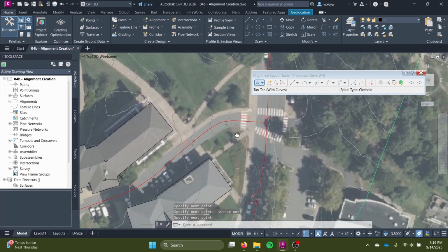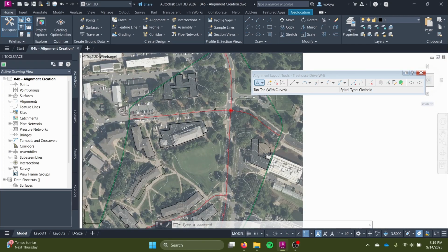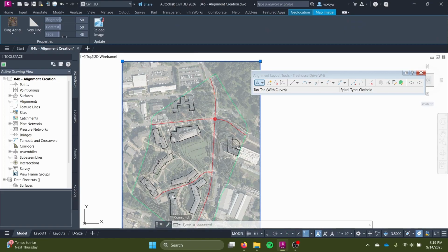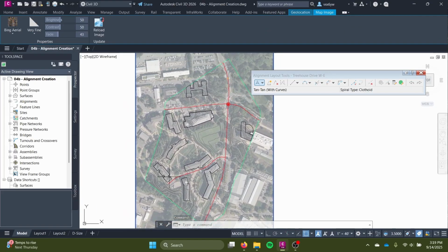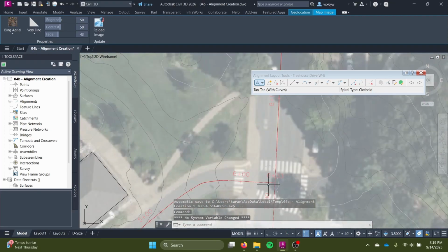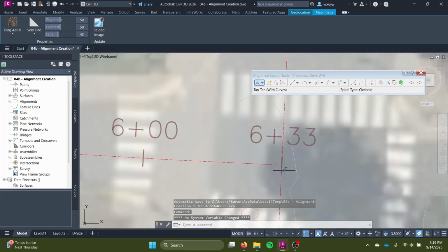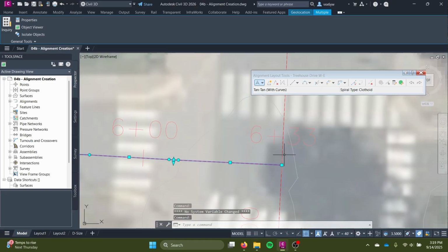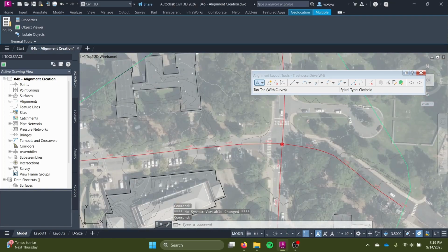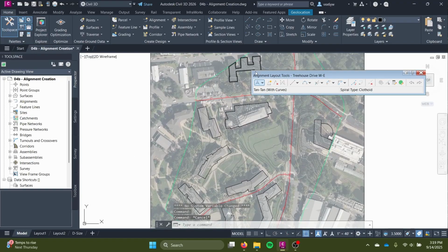All right, I just finished modeling all 3 of my roadways. You can see them here on the map, especially if I turn down the fade a little bit. And this looks pretty good to me. It's following the roadways. I've been in this area before, and that looks pretty good. I also made sure that my alignments intersect at Treehouse and Alderman, and that they intersect at McCormick and Alderman as well. I used the tangent with curves to draw all of this.